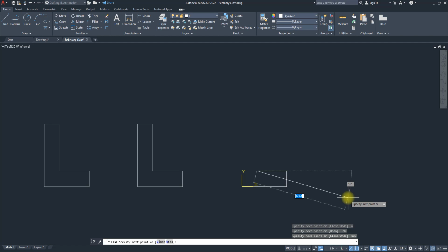So I think it's the 90 that is just flipping. So this is going to be 6, hit tab. If we press 90, it comes down, and we don't want that. That means we want to go up. So it's going to be 6 tab minus 90. Anytime it goes the other way, just undo, do the opposite value. So in this case, 2 tab 180, then C, enter.